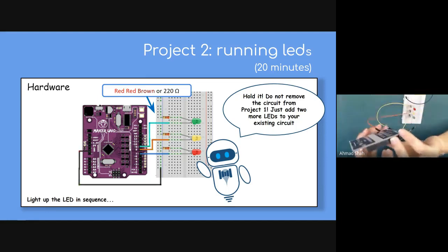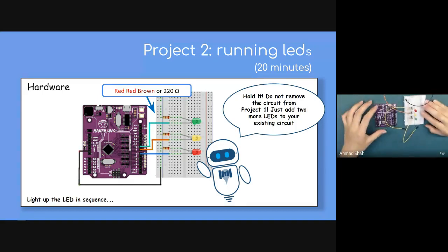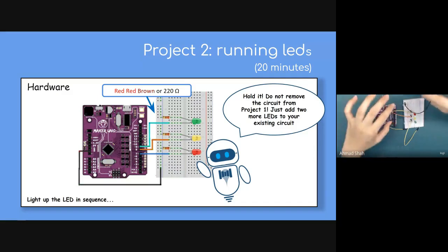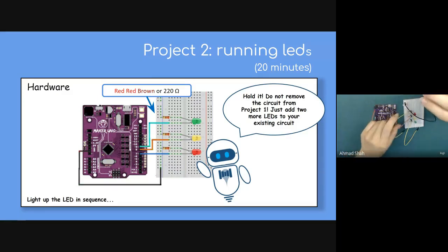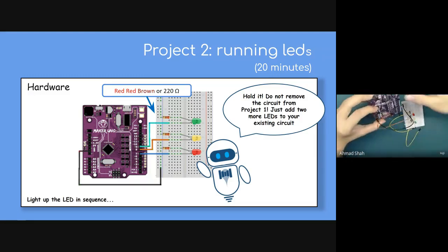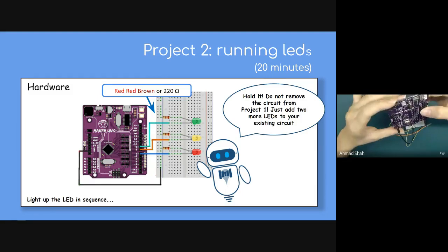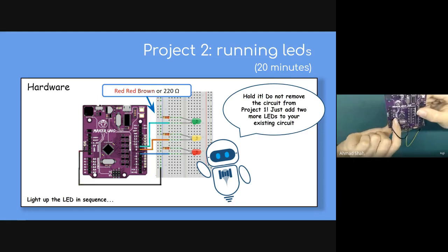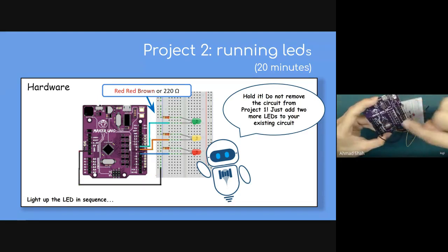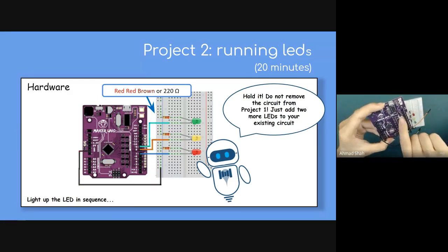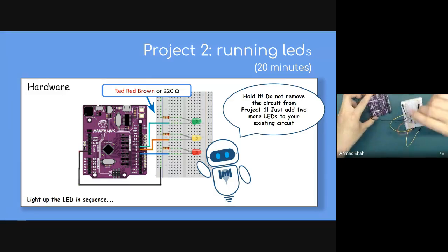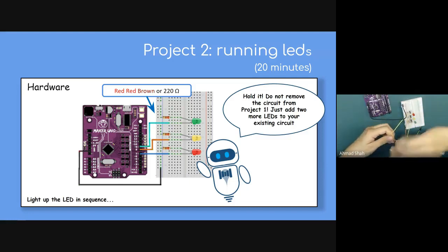So you can now take your Maker Uno. For the ground, which is the black wire for mine, I will connect to ground first. You all know where ground is? Maker Uno ground is here, GND. I think there are 2 pins of ground here and 1 here. But we usually connect to here, the ground near the 5 volt.